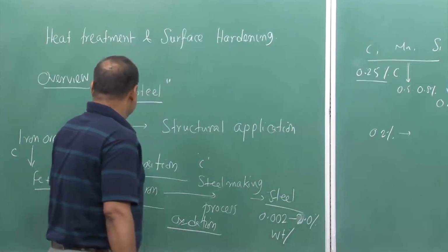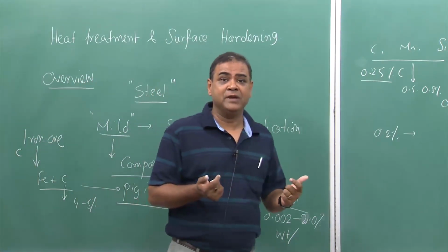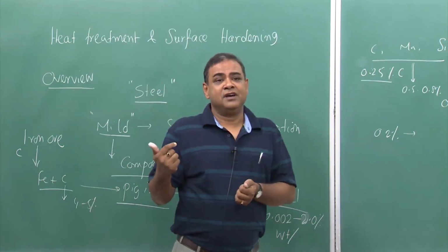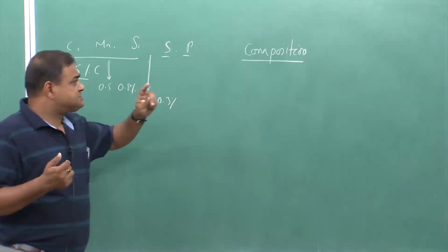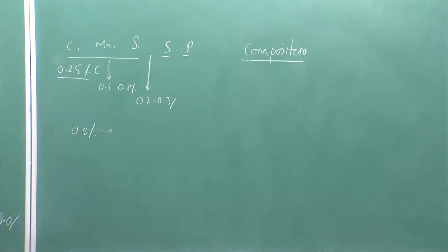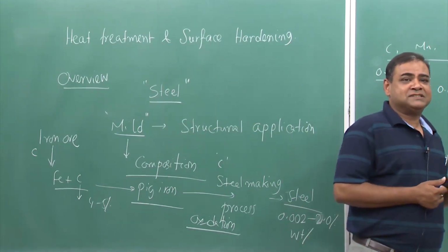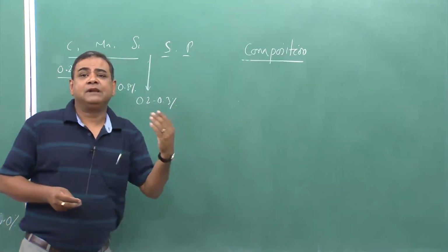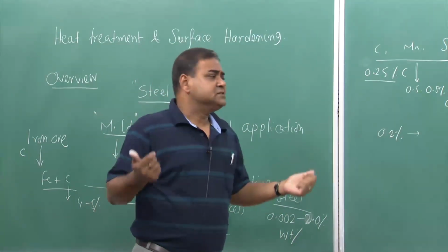For example, if we consider 100% pure iron, which is very difficult to form, 100% pure material is very difficult to form, which will come across during a thermodynamic consideration of alloy formation. You would see that it is extremely difficult to form 100% pure material, because the culprit is nothing but the entropy part. The entropy of mixing disallows us to form 100% pure material. But if we, for example, take 0.0001% carbon steel, which we can consider as pure iron,